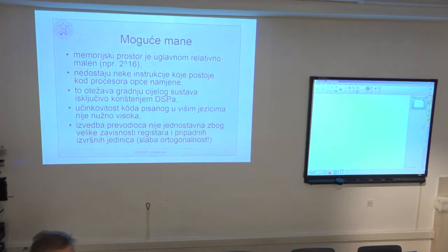Because I have to first transfer these values into these dedicated multiplier input registers, MX0, MY0, and so on, and only then can I implement the multiply instruction. So this non-orthogonality, because you cannot combine any instruction with any of the arguments, complicates automatic compilation of your C code. And the final result is not as efficient as you would like.